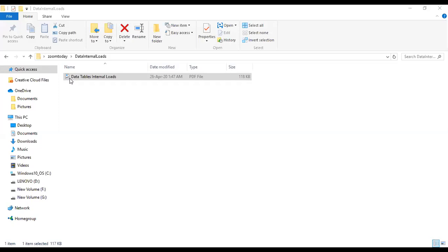And lights are fixed in the false ceiling, hanging in the real ceiling above. And return air goes through. Return air is sucked by the return air duct through the ceiling space. So in this way, it is ventilated. There are holes inside the light body, light casing, and cold air is circulated through this.